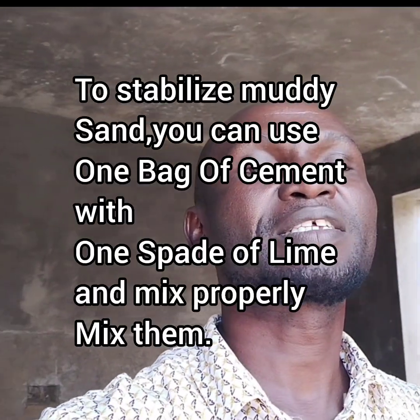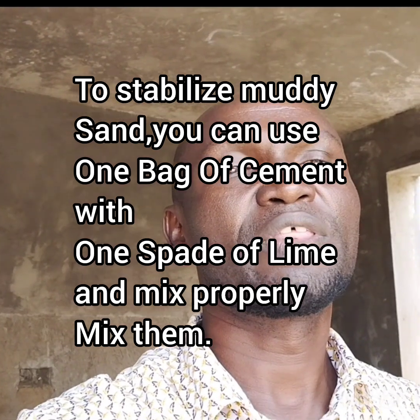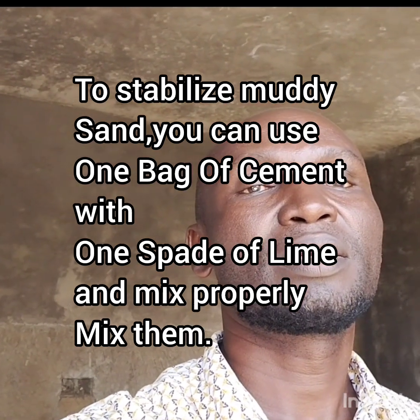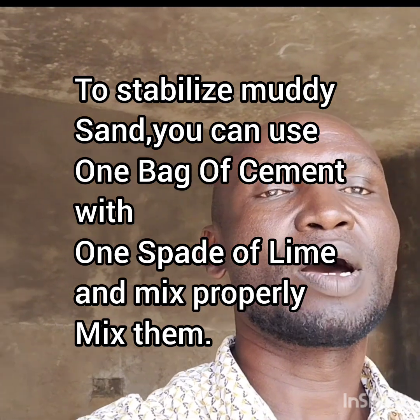If you happen to have sand that has mud, and maybe you're unable to get good quality sand, because sometimes you may not be able to get good quality sand, or maybe it may be too expensive, what you can do is mix that sand with, let's say, 1 bag of cement and maybe 1 spade of lime.